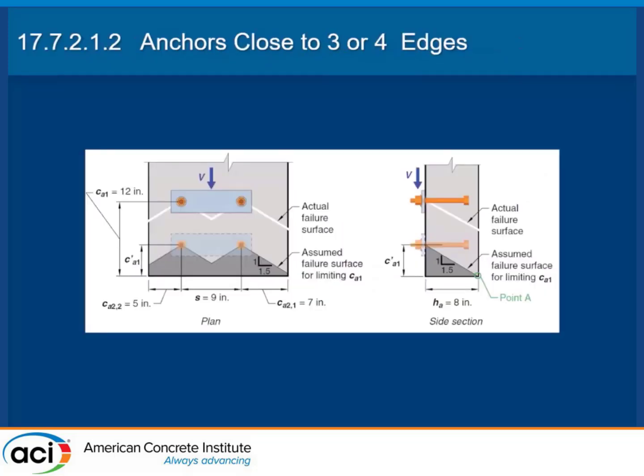Just like h effective, when we were in the top of that pier, your h effective might have been, say, 20 inches, but due to the confines of the top of that pier, it might actually only be 4 inches for your calculations. Same thing happens in shear.